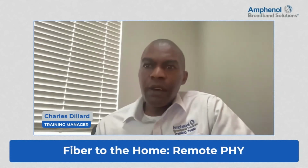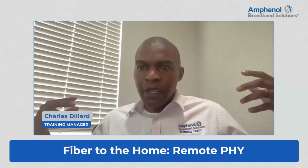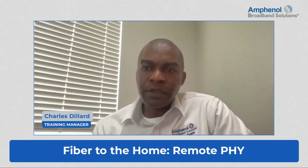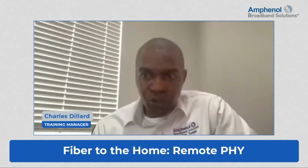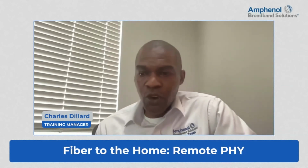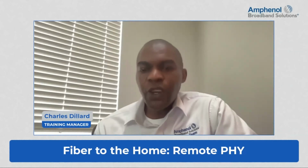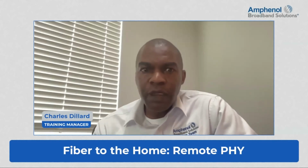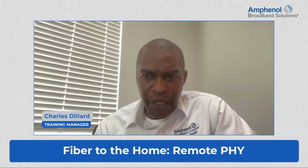Also, with the deployment, it's not something where you're going to come in on a Monday and the plan is to change out every optical node to a Remote PHY device. Some operators may choose to do it with greenfield, so as we are deploying fiber to a new location, they put Remote PHY in instead of just replacing their current HFC nodes, which is really what this training was geared toward.